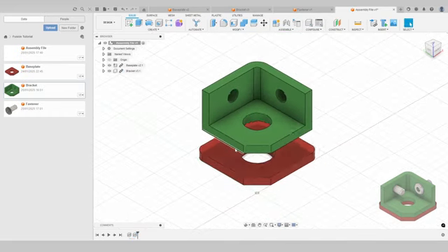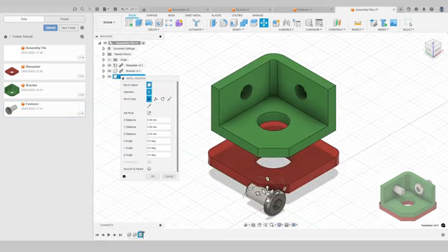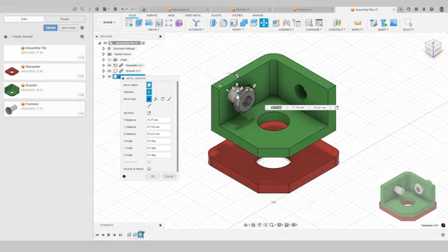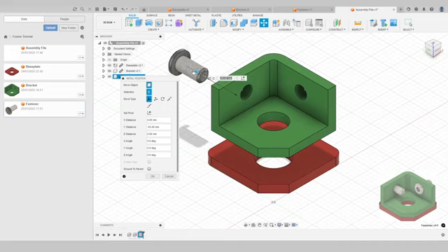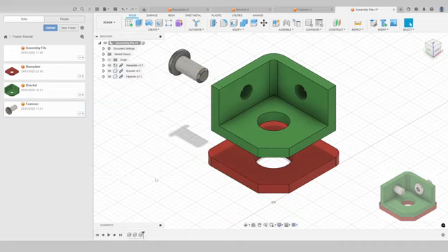That's okay. Now I'm going to go ahead and add in 2 fasteners. So let's throw in one. I'm going to roughly position this. So I'll hold down its center point, bring that over here. I'm going to use this wheel to rotate that by 180 degrees. I just offset that slightly as well. I want to form a joint between this hole and this fastener. Press OK.